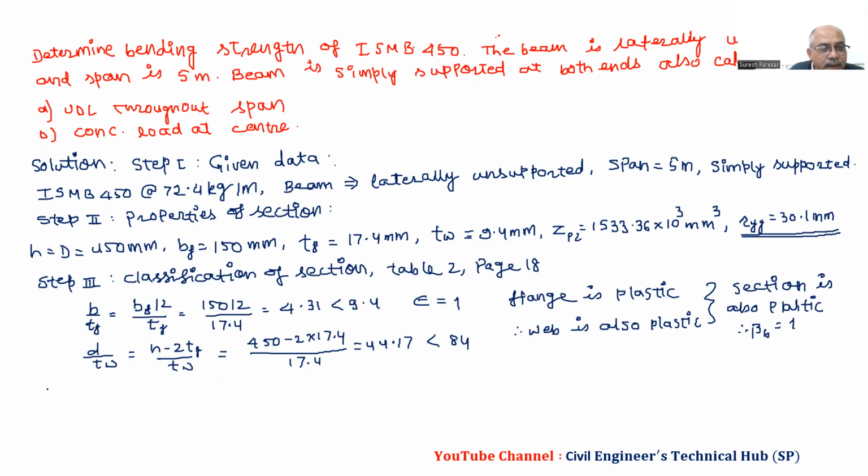And then we have step 4, which is bending strength. As the beam is laterally unsupported, we have to go to clause number 8.2.2, page number 54.